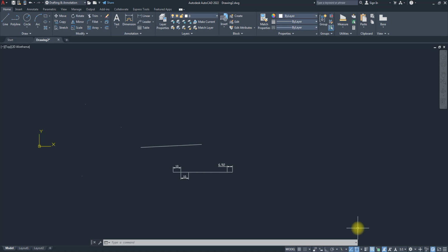If I want to change the elevation of any object I create, first off, what I need to do is run the elevation command. You don't like commands, but you have to know some. So I run ELEV for elevation, and press enter. It asks me for an elevation value. The default value is 0. If I put an elevation value of, let's say, 10, it's then asking me to put a thickness. I'll just leave that there.